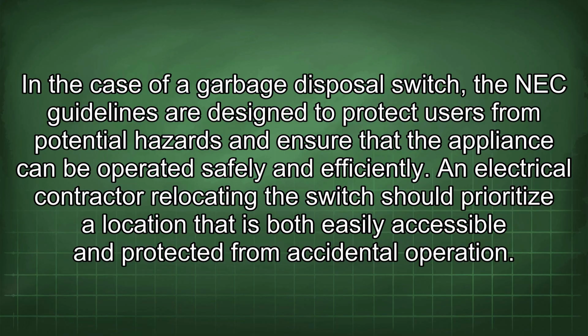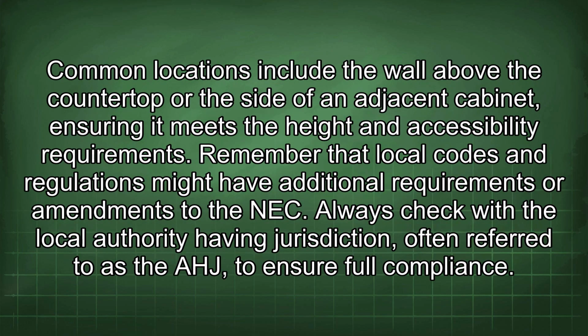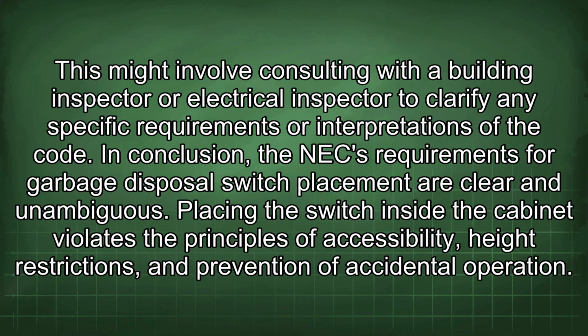An electrical contractor relocating the switch should prioritize a location that is both easily accessible and protected from accidental operation. Common locations include the wall above the countertop or the side of an adjacent cabinet, ensuring it meets the height and accessibility requirements. Remember that local codes and regulations might have additional requirements or amendments to the NEC. Always check with the local authority having jurisdiction, often referred to as the AHJ, to ensure full compliance. This might involve consulting with a building inspector or electrical inspector to clarify any specific requirements or interpretations of the code.